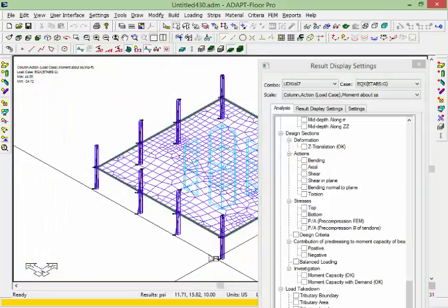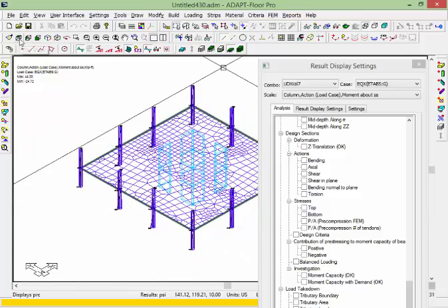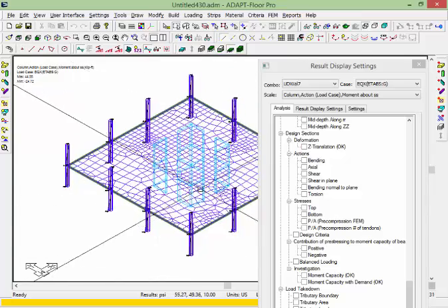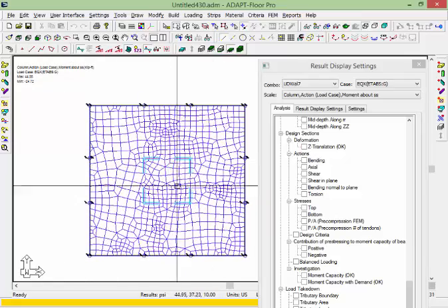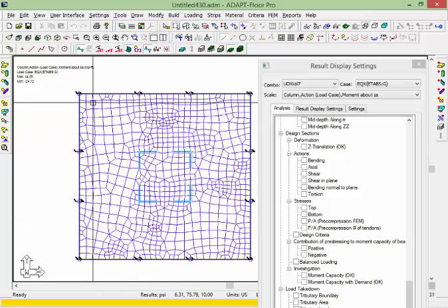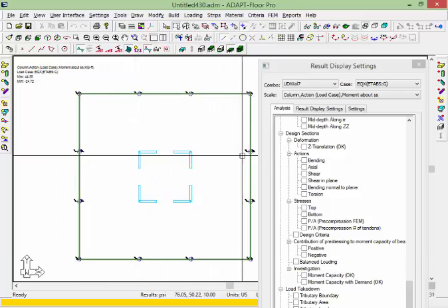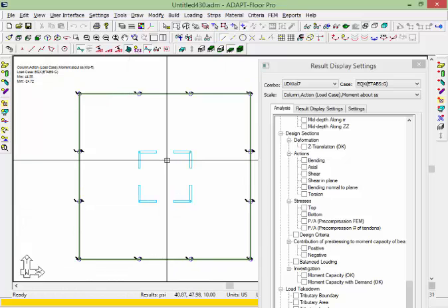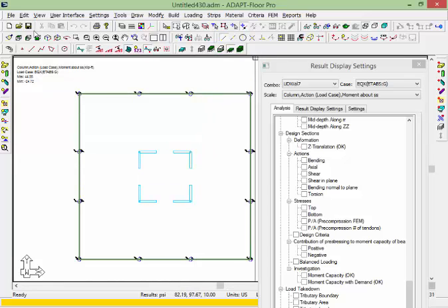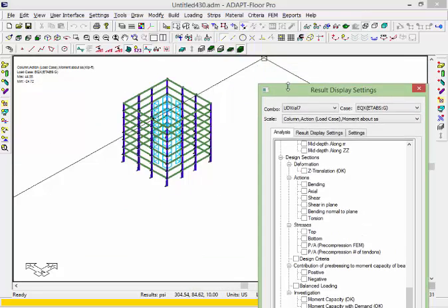We now have the solution for this rerun, and if the intent is to design the floor slab for combined gravity and lateral actions, we could then go in, and similar to what we would do with a regular Builder model, we would set up support lines and strips along each of the directional frame lines, both in the X and the Y direction, and obtain solutions for the slab design. We'll go ahead and go back to multi-story mode.